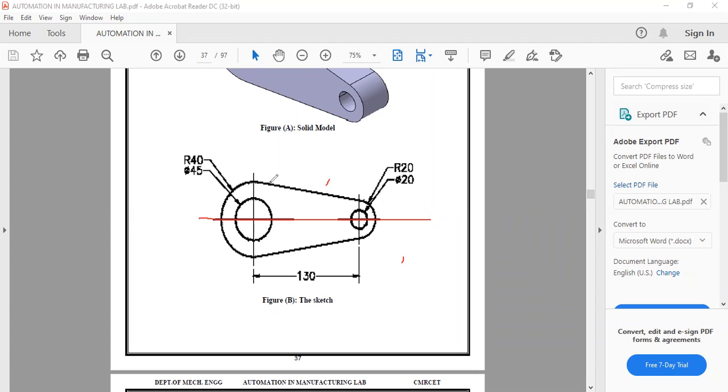So that was there, and we had drawn these inner circles, right? We used concentric constraints to define them, because we don't know if they are at the exact center. They are actually concentric as per this drawing, but when we draw, we just draw some random circle. We will select this circle, this arc basically, and then go to the constraint defining dialog box and select concentric, so that we can tell the software that these circles have the same center.